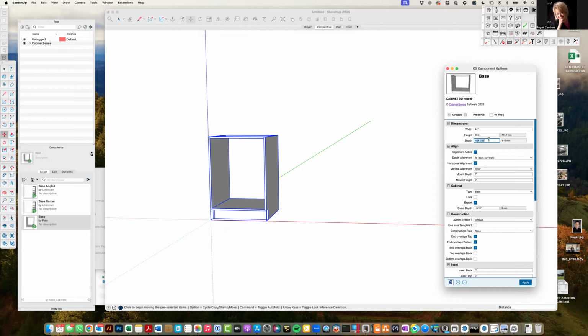For this particular one, the countertop is going to be 30, and what did you say drawer slides are, Josh? 27? Yeah, drawer slides are in increments of 3 inches, so we'd probably want to go 28 and a half for the carcass depth. Yeah, we need to be able to put a 27-inch drawer slide in this thing. Gotcha. Do you have a standard depth of cabinets though? What we typically do is the 24. Yeah. Okay, all right.